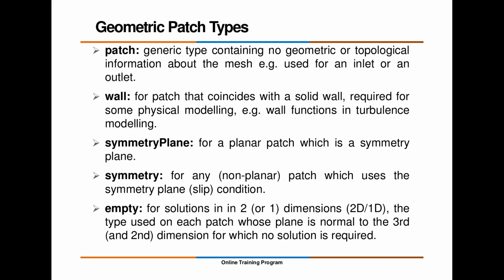We create a half portion through the axis and work with either the top half or the bottom half, and that way we can specify the symmetric plane boundary condition where the axis cuts the plane. That is called the symmetric type condition. Wherever the physics is symmetric as well as the geometry is similar with respect to a plane, at that point people normally use the symmetric plane condition.